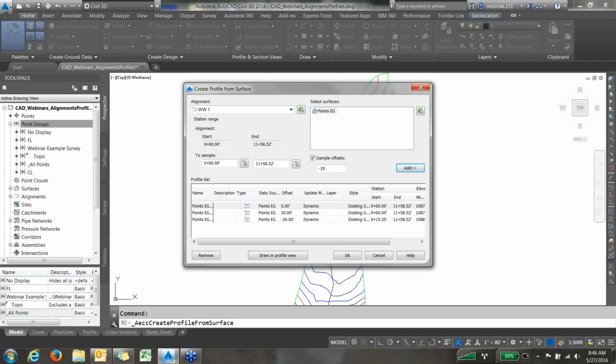Now you'll have to know approximately what kind of width that you might be dealing with, and that's based on experience. So typically 40-foot waterway is what we deal with. So a half width is going to be 20 foot, so that's why I chose positive 20 and -20. If you had a 32-foot wide waterway, then you would choose 16.